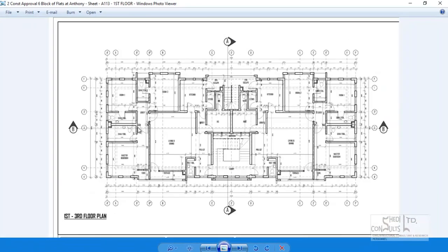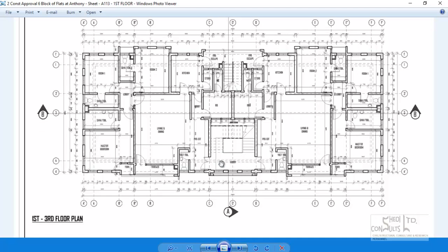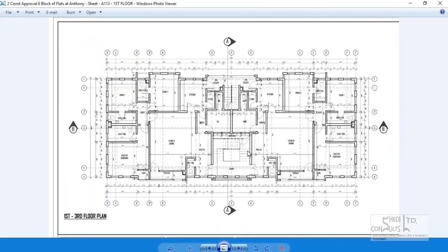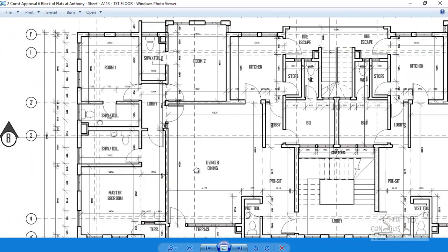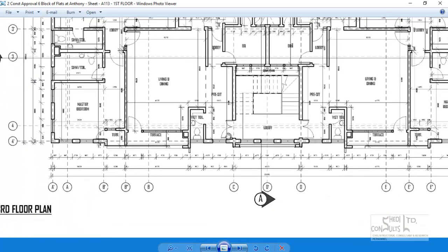Once you get an architectural design like this, the first thing you need to do is study it. The responsibility of a structural engineer is to frame the building, providing the structural framing arrangement of all the structural entities that will support the entire structure. These entities, which are the skeleton of the structure, comprise the structural beams, the structural columns, the structural slab, the structural foundation, and the structural access stair.